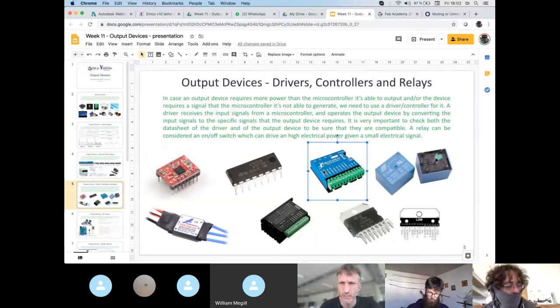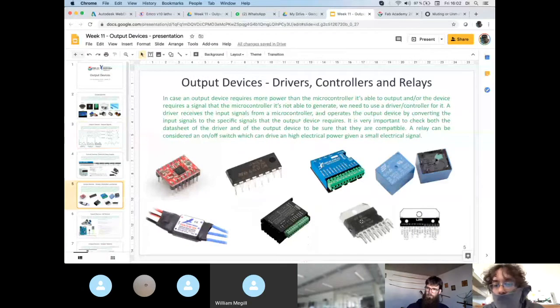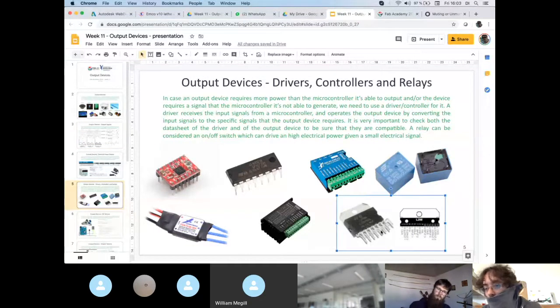One thing that is worth mentioning is that inside the stepper driver, the basic mechanism that allows you to generate this kind of signal, high or low over here, is called the H-bridge. So you can have an H-bridge as a separate component, like this L298 is an H-bridge.